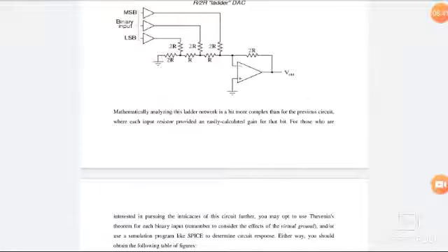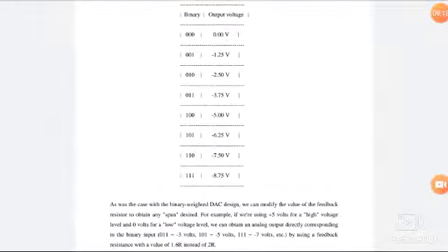Mathematically analyzing this ladder network is a bit more complex than for the previous circuit, where each input resistor provided an easily calculated gain for that bit. For those who are interested in pursuing the intricacies of the circuit further, you may opt to use Thevenin's theorem for each binary input, remembering to consider the effects of virtual ground, or use a simulation program like SPICE to determine circuit response. Either way, you should obtain the following table of figures,